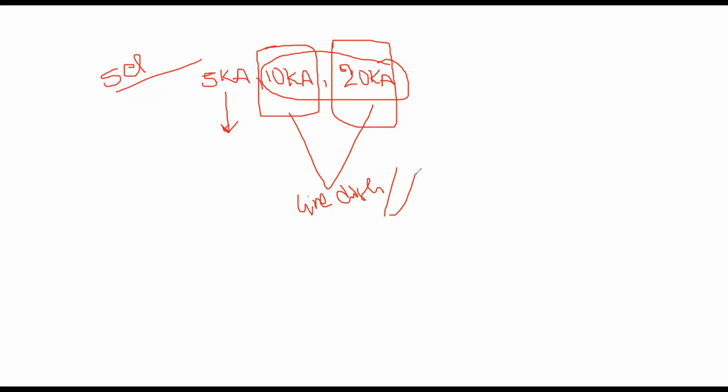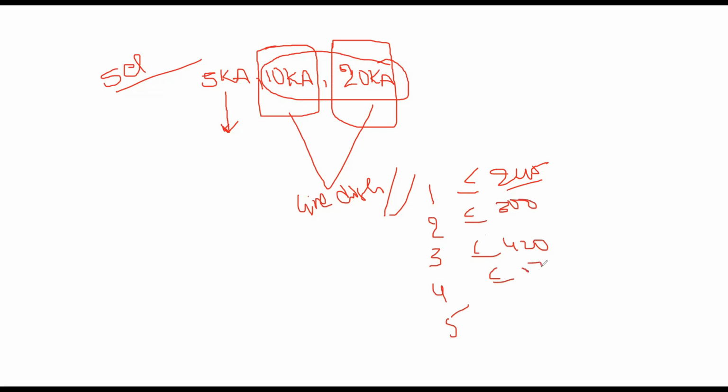In the line discharge classes, generally for less than 245 kV system, class 1. We have 5 classes of line discharge: less than 245 kV, 1; less than 300, 2; less than 420 kV, 3; less than 550, less than 850, we have different classes. And these line discharge classes can also be categorized with the MO blocks, metal oxide blocks.